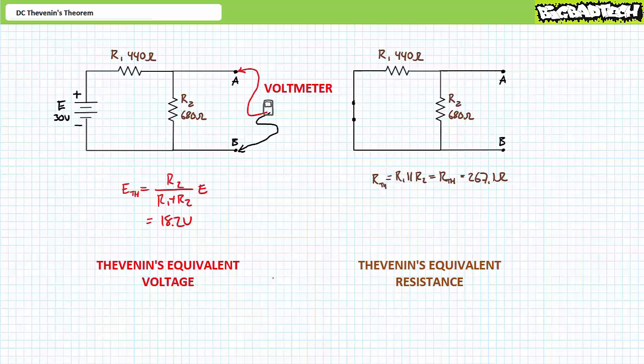To experimentally observe RTH, first one must remove the load resistor from the nodes of interest. Next, one would remove the source or sources from consideration. One removes a voltage source by replacing it with a short. Note, do not short out a real voltage source. This is a surefire way to get stuck in the iron chair position for the rest of your academic career. Remove the voltage source first. Replace the terminals formerly occupied by the voltage source with a short or 0 ohm resistor.